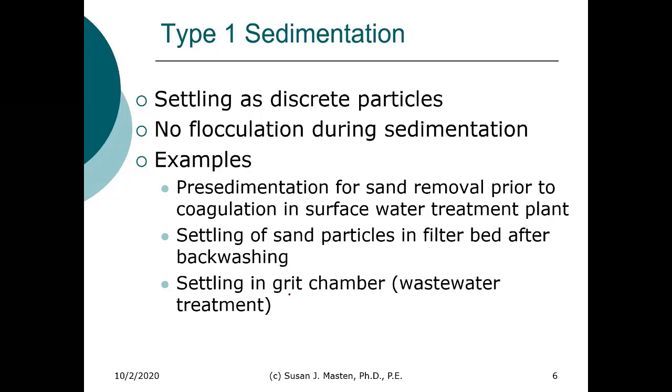In wastewater treatment, we typically will have what we refer to as a grit chamber. So we're removing predominantly inorganic material, kind of the size of coffee grinds. It's silt, coffee grinds, eggshells, particles that get put down the drain. And these need to be removed before subsequent treatment to protect your pumps. And then in a quiet stream, sand particles will settle by type 1 sedimentation.